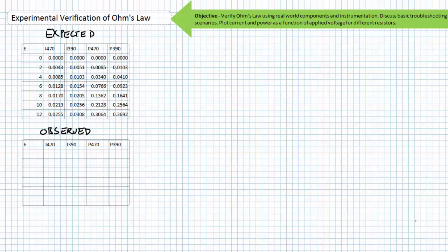First up, we need a 470 ohm resistor. What's a 4-band color code for a 470 ohm resistor? 4 is yellow, 7 is purple, brown means it's followed by 1 0. We'll use a plus or minus 5%, so the last band is gold. Yellow, purple, brown, gold. Go fetch.